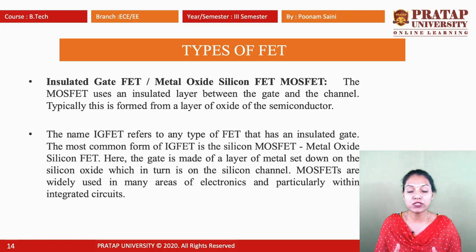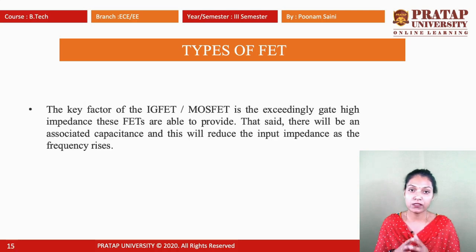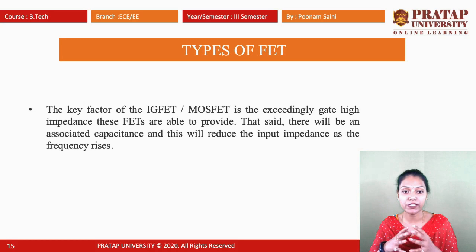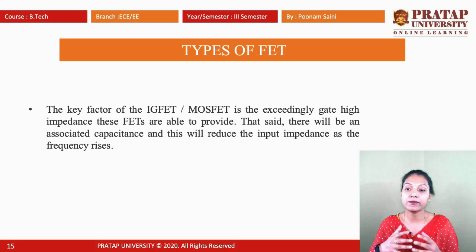MOSFETs are widely used in many areas of electronics, and particularly within integrated circuits. Today we use MOSFETs widely in electronics as well as in integrated circuits. When we go through the next slides and talk about integrated circuits, we have to talk about the metal oxide layers. The key factor of IGFETs and MOSFETs is the extremely high gate impedance that FETs are able to provide. That said, there will be an associated capacitance from the insulated gate, and this will reduce the input impedance as the frequency rises.